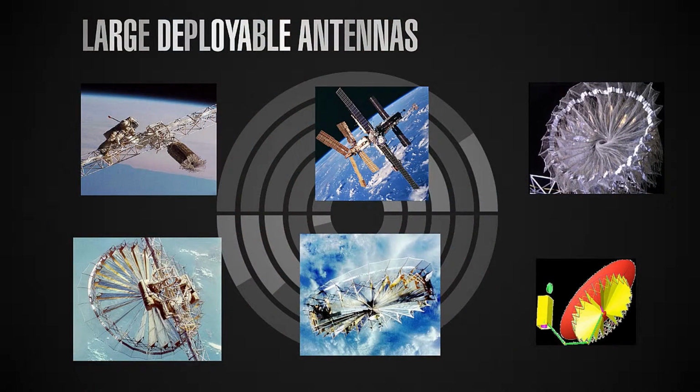So those are the reflectors that were mentioned in a previous lesson, able to generate a very fine coverage of the Earth with very small spot beams. And those spot beams have a very high gain, because I remind myself and you that narrow spot beams, so narrow beamwidths, correspond to high directivities, high gain over the coverage. Those spot beams allow the use of a very simple terminal that can be portable.